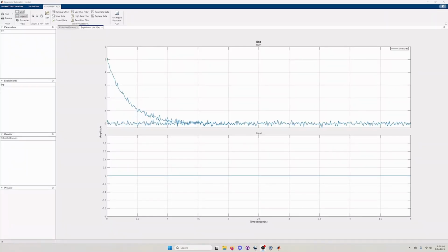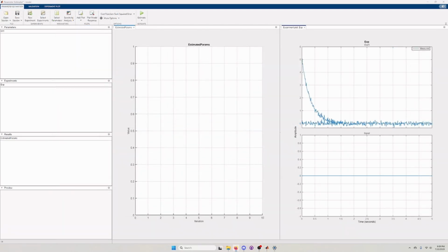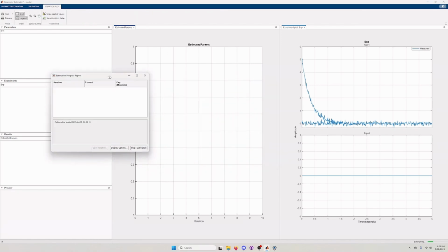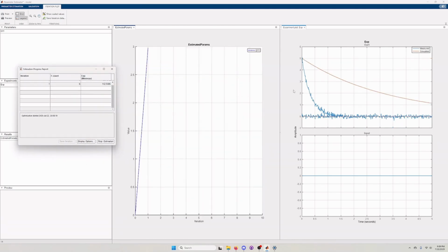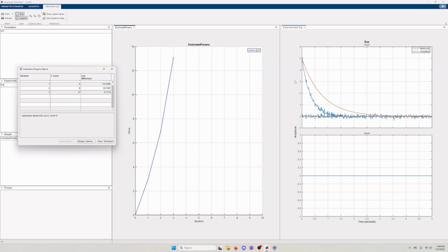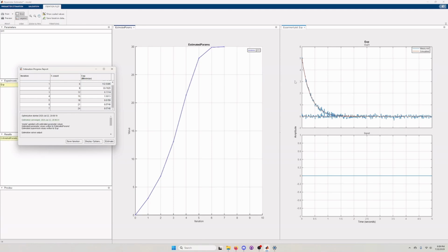Here is an example using the tool to estimate the drag coefficient on one face of the vehicle. We used case studies like these to learn the parameter estimation tool with simulated data before using it on our real vehicle. In the simulation, the vehicle's thrusters are turned off and it begins at a velocity of 5 meters per second. Due to the quadratic drag coefficient set to 30, the forward velocity quickly decays to 0. Using the thruster forces of 0 as the input and the velocity measurements as the output, we see the parameter estimation tool quickly converges to the correct drag coefficient, even with a bad initial guess.